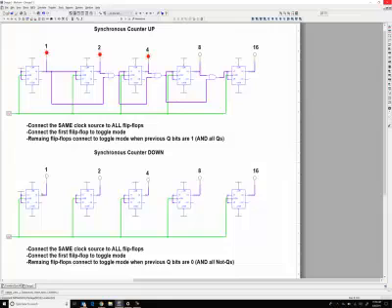Now what we're going to do to make it count down, or in reverse, is make sure that JK have a 1 when the previous bit is off. Well, how do we get a 1 when it's a 0? If you said, yeah, connect to the not Q, you're right. Now there's supposed to be a little inverter symbol here that's not shown, but that's okay, it's a little bug.